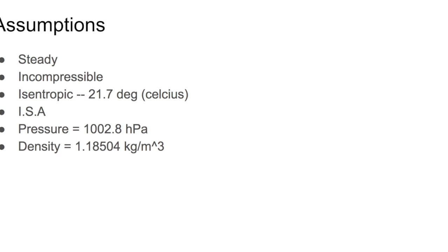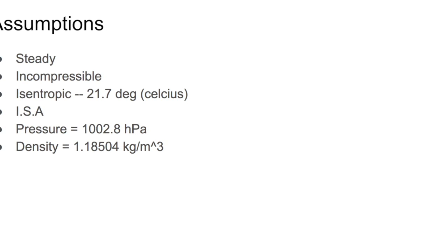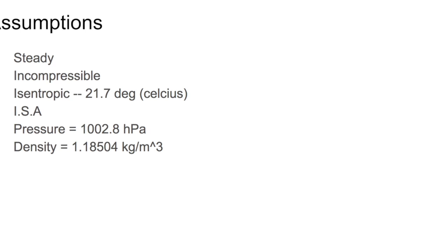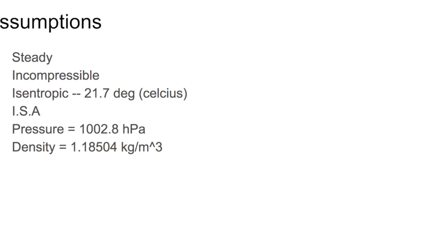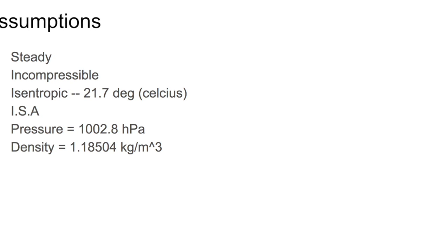On the day of the test, the pressure was about 1,000 hectopascals, the temperature was about 21.7 degrees Celsius, and thus our density was about 1.185 kilograms per cubic meter.